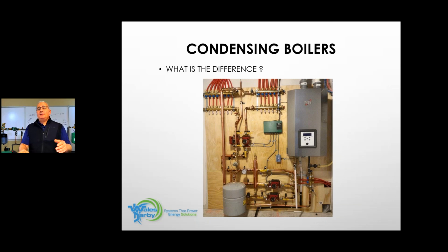Proper maintenance, we should get 15, 20 years out of these systems, all being installed properly, vented properly. We have a class on venting coming up, so we're going to talk about that in detail. So if they're vented properly, piped properly, and maintained, you can get good service life out of them. And the maintenance is not a big deal. If you set it up right on the install, maintenance is pretty easy. It's a once a year you're getting in there, cleaning out the heat exchanger. If you got the filter in front for the combi side, that combi will be nice and clean, and you really shouldn't have any difference there.